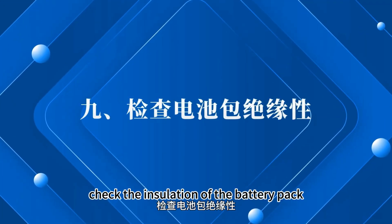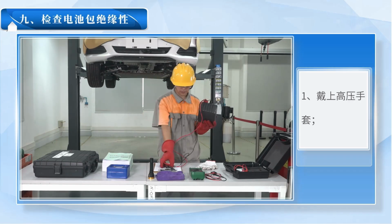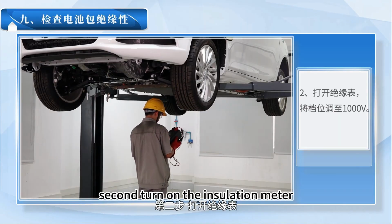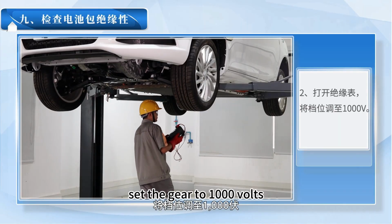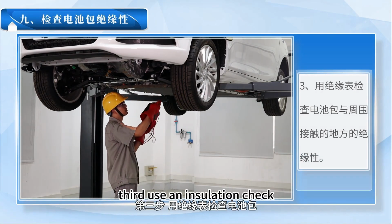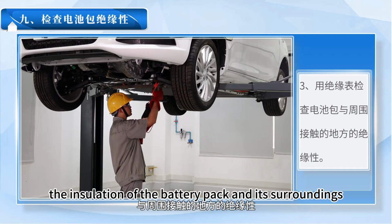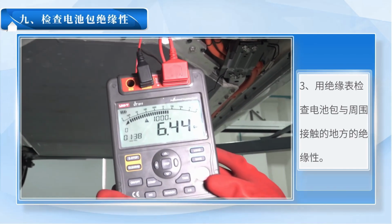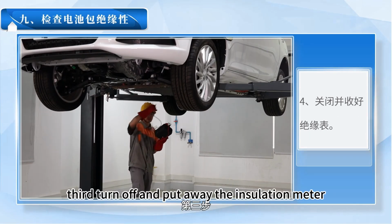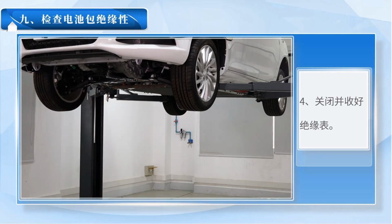Check the insulation of the battery pack. First, put on high voltage insulating gloves. Second, turn on the insulation meter. Set the gear to 1000 volts. Third, use the insulation meter to check the insulation of the battery pack and its surroundings. Fourth, turn off and put away the insulation meter.